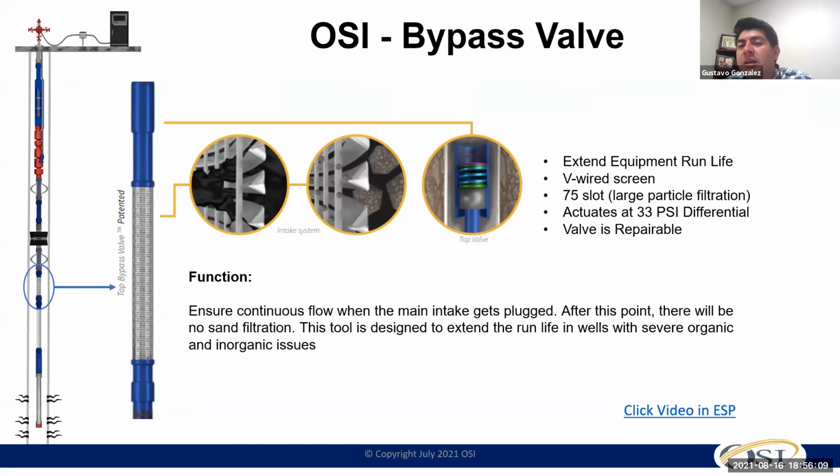We went with a tungsten shaft. We designed the pump to be a stronger system that can handle that erosion, that compaction of sand, and that crushing that you're going to see for the stages. But again, we come back now to other fields and you really have enough flowback that you're able to just put in a standard pump and you can achieve a decent 1 year runtime.